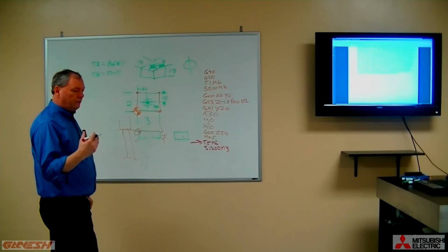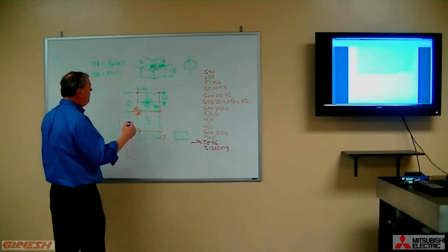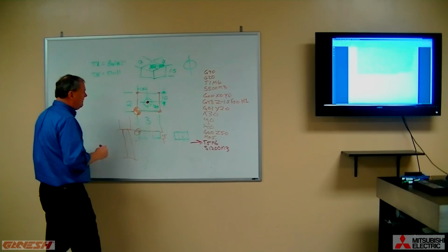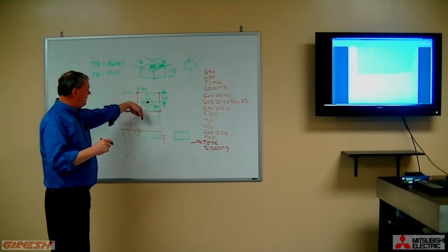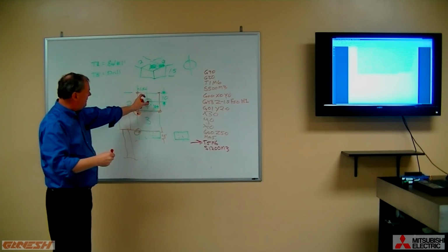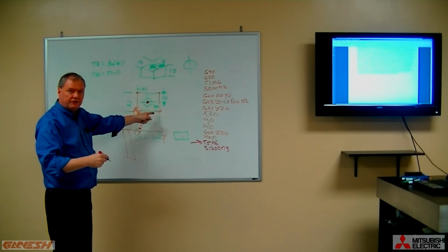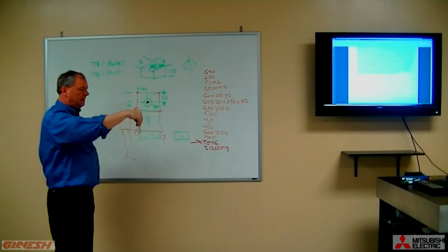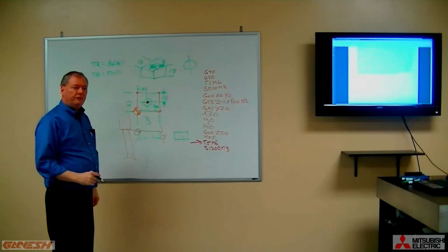And now I'm going to do what is called a single point drilling operation. Think about it. All we need to do to drill a hole is position over the hole. The drill is already a ½ inch, so we don't need to do circular interpolation. We simply need to go down with the drill and then come back out of the piece, and we're finished.